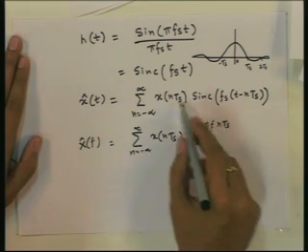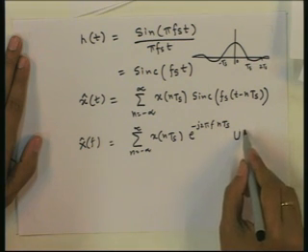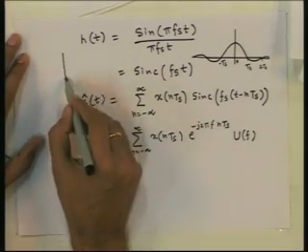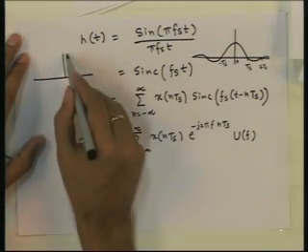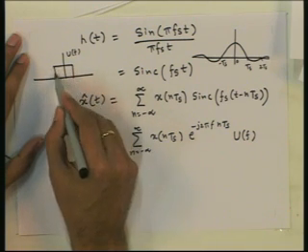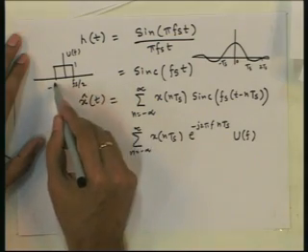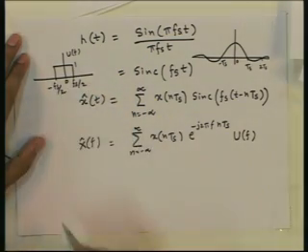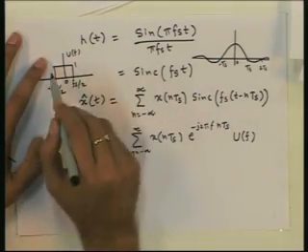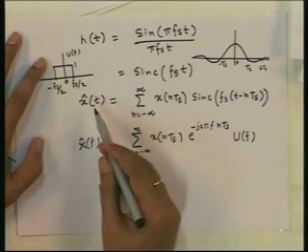And then the Fourier transform of the sinc is the rectangular function, which is one from minus Fs by 2 to Fs by 2. This is U f, which is also H f, the frequency response of the filter.